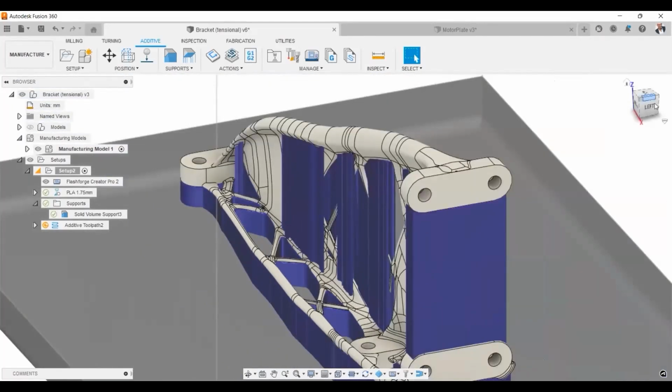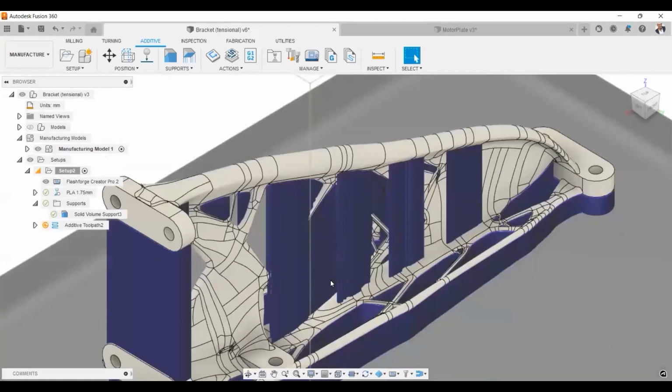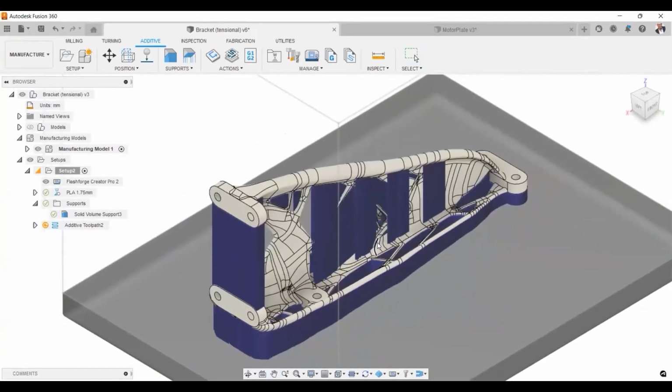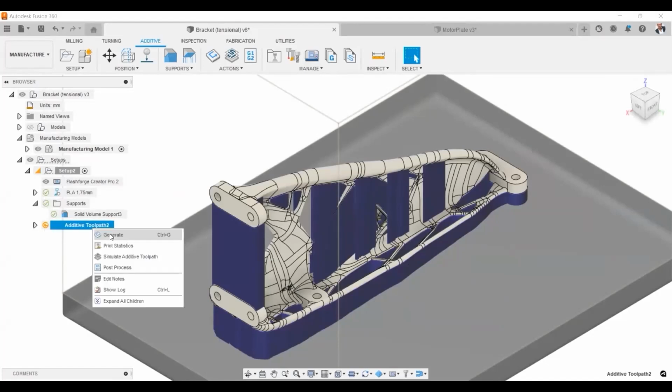But the best way we could have done this is to use a different filament, since the printer we selected has 2 extruders, unlike most printers that have 1 extruder. So what we could have done is maybe use PLA or ABS, let's say ABS for printing, and then use PVA on the other extruder to print the support. So these are things we could really explore in that regard. So we can now go ahead and do the final slicing.